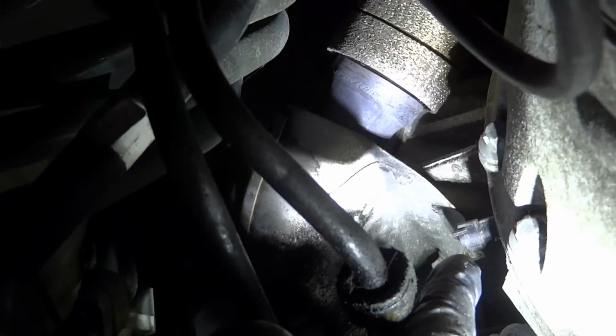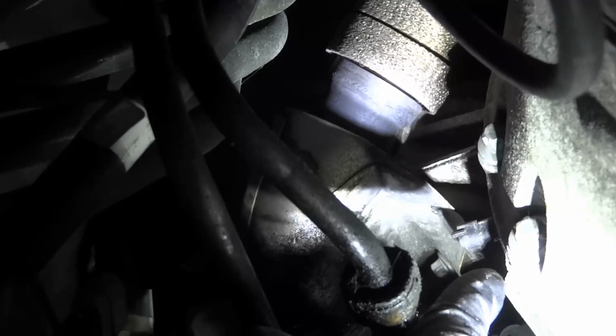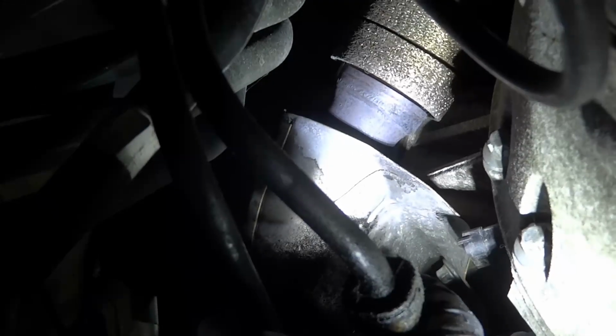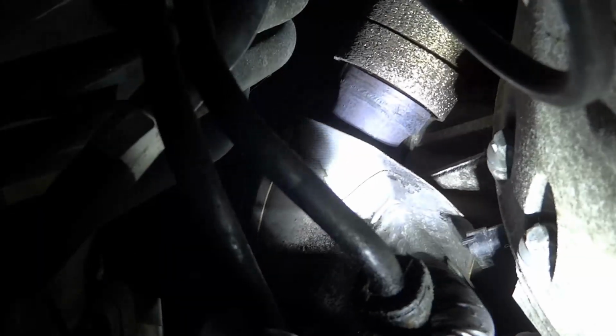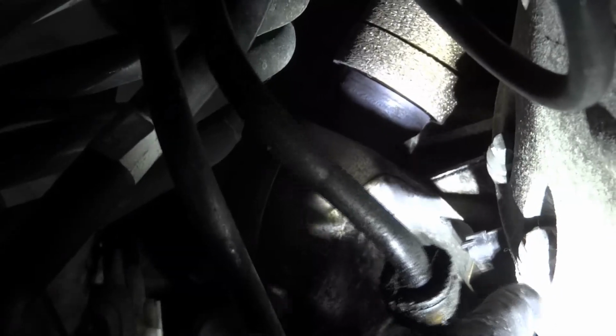The sensor has 1 bolt that bolts it onto the bell housing. I'm gonna remove that bolt and slide the sensor out. Once I pull the sensor out, I'm gonna inspect the trigger wheel through the sensor hole. I'll have someone bump the key while I'm inspecting the trigger wheel. So when someone bumps the key, so basically someone is gonna crank the engine, and what I will be looking at is the trigger wheel spinning.